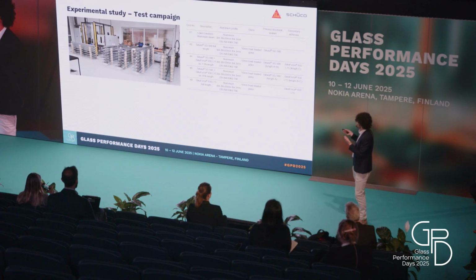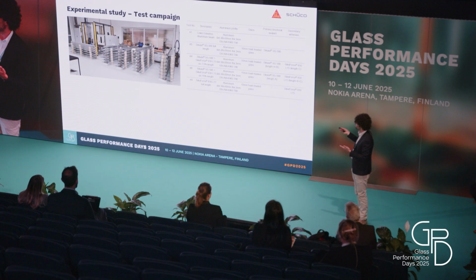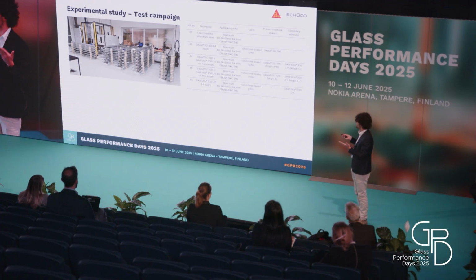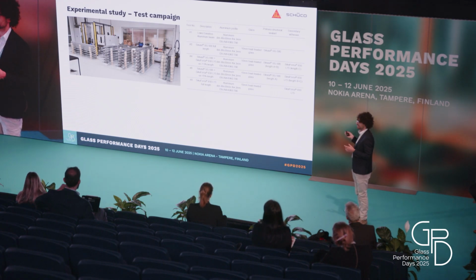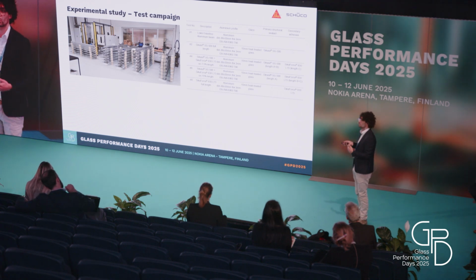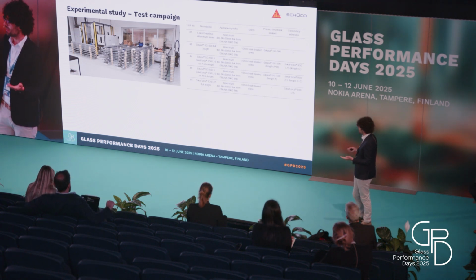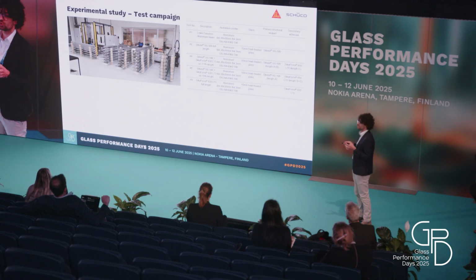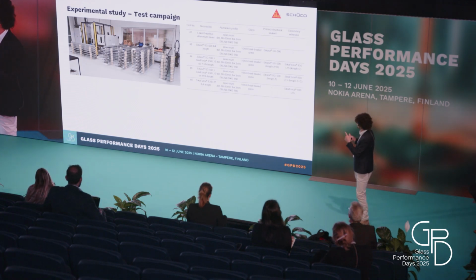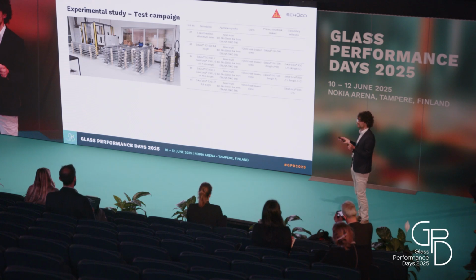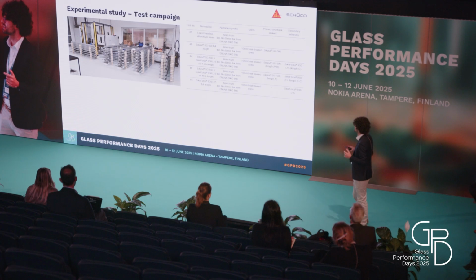And then we did the series number 4 and 6, with structural silicone SG500 from Sika at the center, and then at the edges we put Sika Force 930, that Pedro will talk more about. It's a polyurethane. And we put it in 2 different lengths, so you will see soon: 250 millimeters on both sides, and 450 millimeters on both sides.